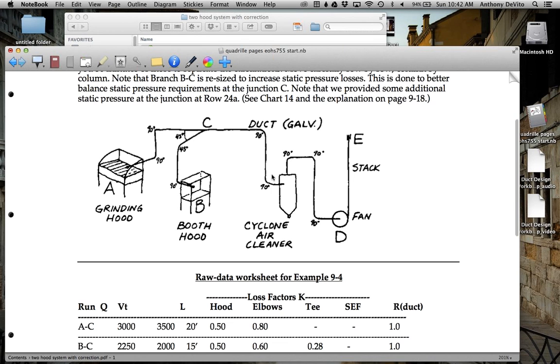If you're interested in what calculation it's doing, you can click into that cell in the spreadsheet and see the formula that it's using, what cell it's adding or multiplying, and so on and so forth. Or even better, in the textbook, there is a chart that mirrors this spreadsheet, except it's meant for manual calculation. And if you use that, the formulas are right there. It tells you what formula to use to calculate static pressure based on the information that you've put in advance of that.